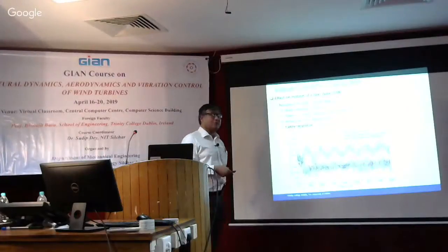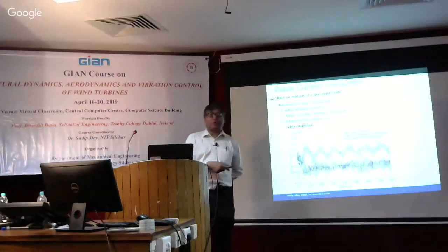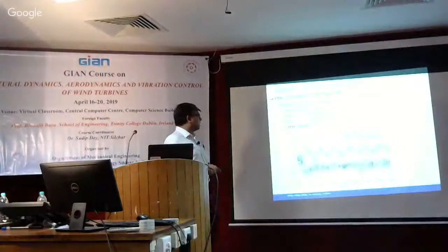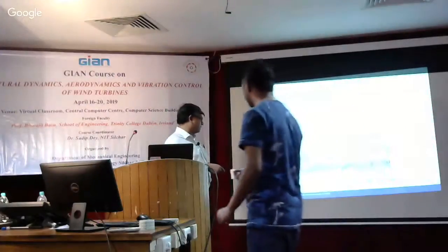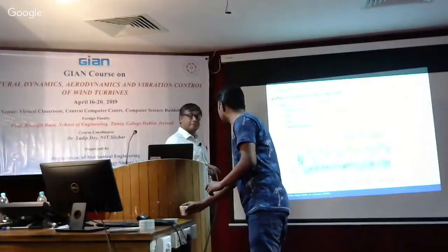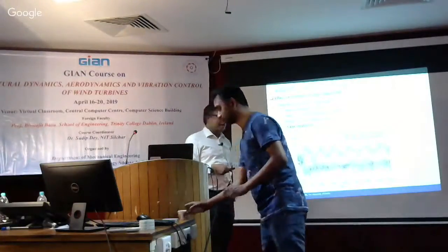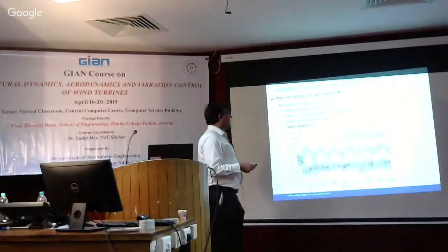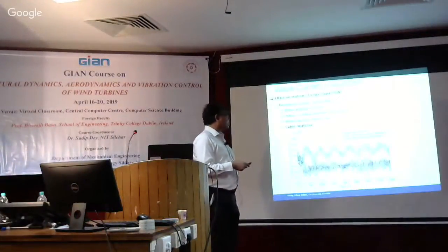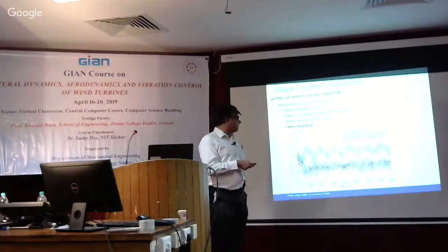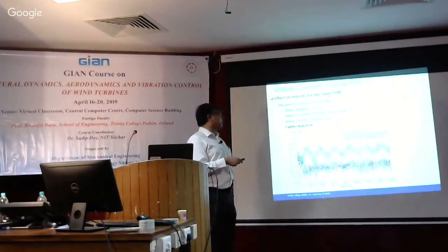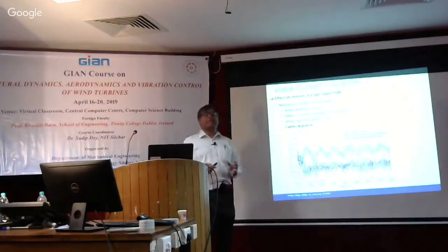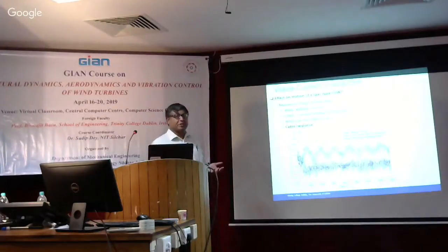So obviously for offshore wind turbines, the current is very important to consider. And not only that, you can also see that the red and the blue curves, maybe not so much in the maximum value, but in the variance, they are also different. So that means without the current, obviously it's significantly different. Even with the current, if you do not take the interaction into account, then the response is also different.